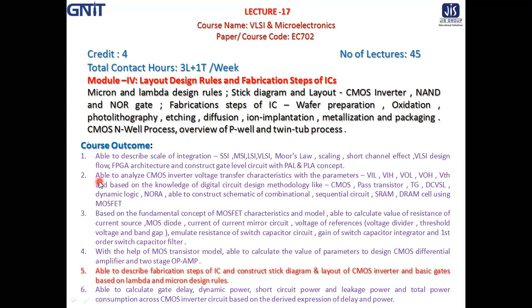The second course outcome is to be able to analyze CMOS inverter voltage transfer characteristics with the parameters VIL, VOL, VOH, etc. and VTH, based on the knowledge of digital circuit design methodologies like CMOS, pass transistor, transmission logic, DCVSL, dynamic logic, NORA logic, and to be able to construct schematics of combinational and sequential circuits, SRAM, and DRAM cells using the MOSFET.